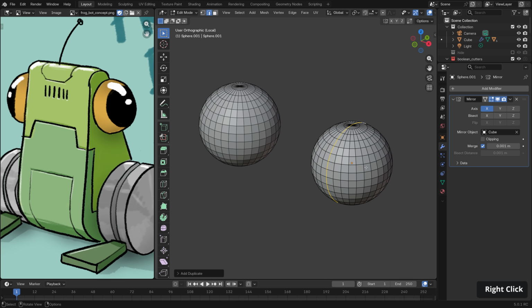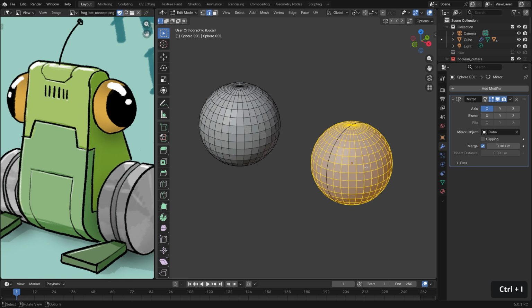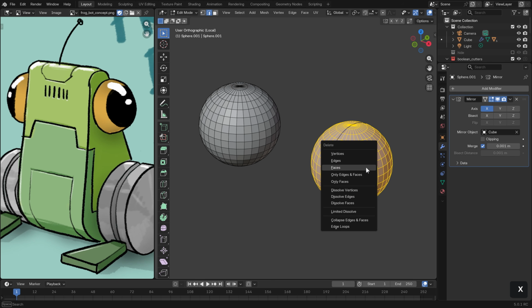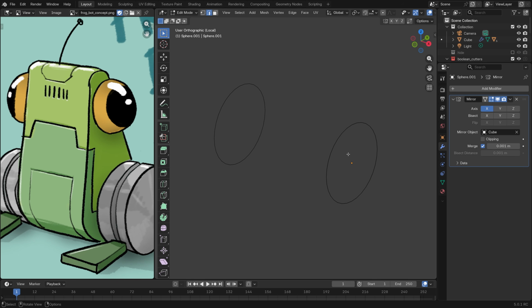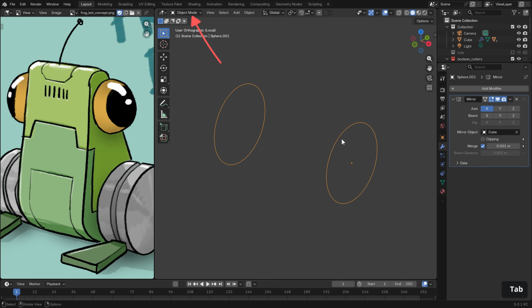to drop. This time we can do Control and I to fully invert the selection. So we're selecting everything but that new circle we just created, then X and delete vertices, the fundamental data of our geometry, to ensure that everything selected has gone. Jumping back out into object mode, and we are left with 2 circles here, but the only reason there are 2 is because of our mirror modifier. So let's jump into our modifier options and apply the mirror modifier like so.